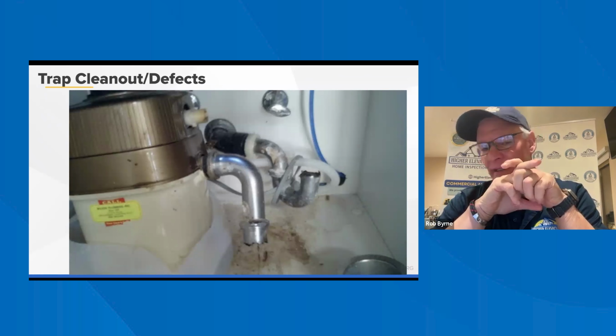A lot of builders as well will hire us to go in and do drawer inspections to look for these things while the wall is open, and then you can comment on them. But this is talking about how gas pipes and slabs should be protected. You would see all of that during the construction phase, because once the concrete is poured, you'll have an idea if it's coming out at the termination points, but you don't know what's going on in there.